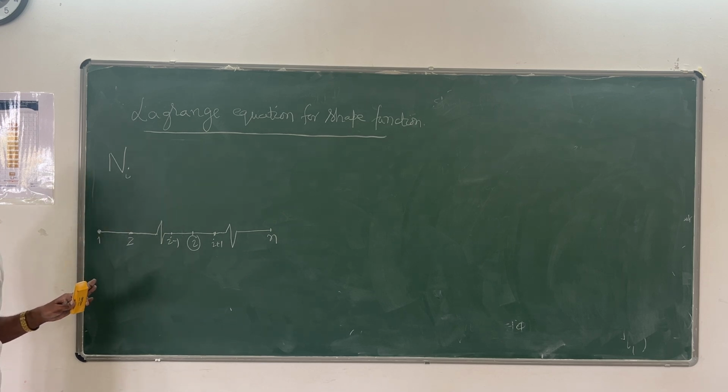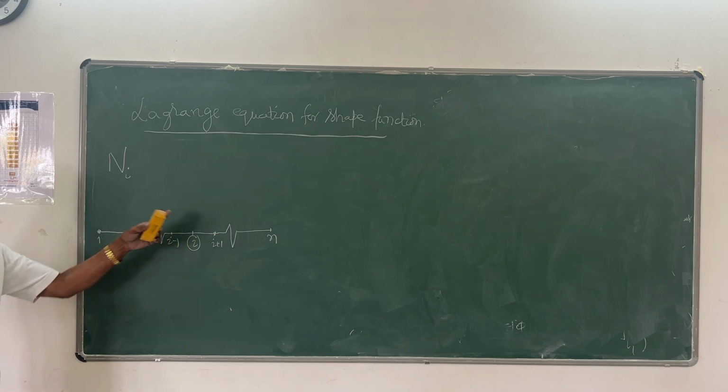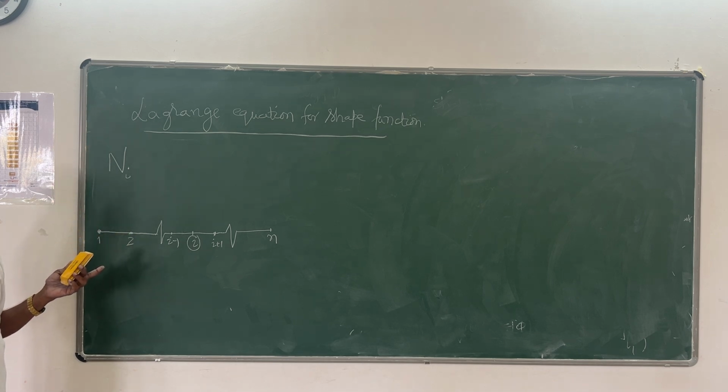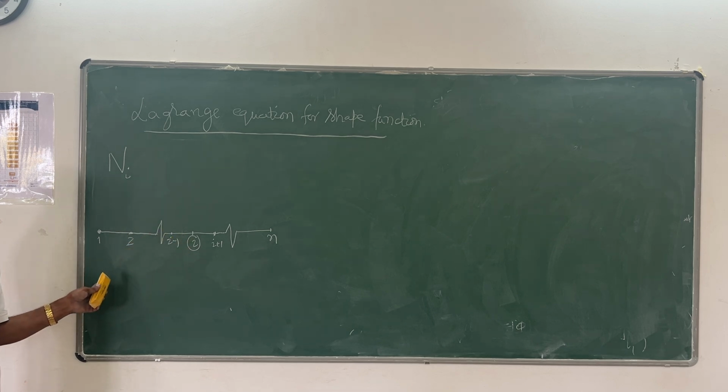If you take that concept, then it can be applicable for a quadrilateral also. For integrating and differentiating, you have to use partial derivatives only. And you have to use the Jacobian for finding the interrelationship between the natural coordinates and the global coordinates. You have to use the Jacobian transformation, not the regular thing.